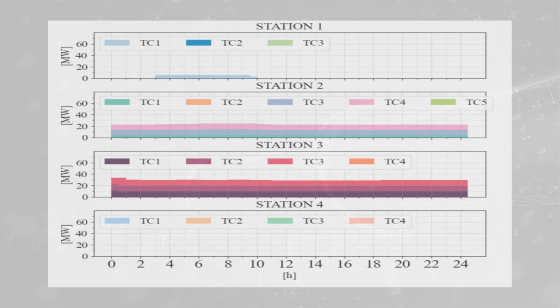The optimal unit commitment and load of the gas turbine-driven compressors, GTDC, is shown in the figure. The solution uses only one GTDC of station S1, 3 GTDCs of different sizes in stations S2 and S3, while station S4 is always in the bypass mode. The optimized solution features an objective function which is 7% lower than a preliminary solution found by fixing the commitment of the GTDCs S1 to S3, optimizing only the loads.